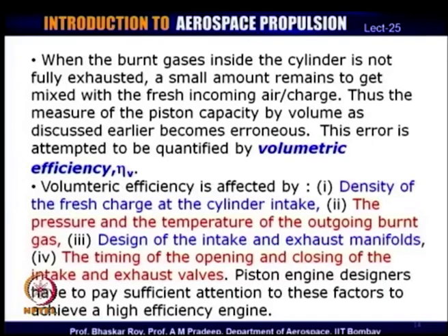And as a result, effectively the piston capacity, the volume with which you have been talking about, effectively gets reduced. This error is attempted to be now quantified through a term which we call volumetric efficiency.